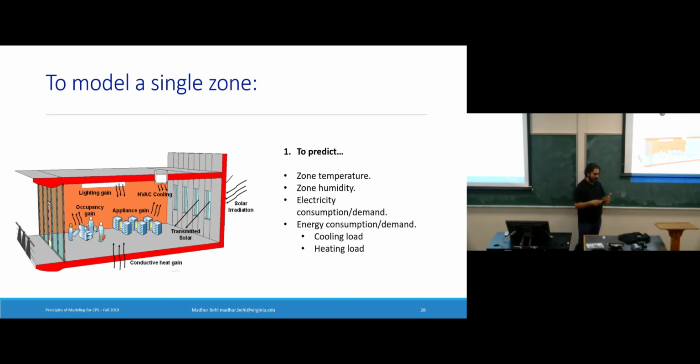And this is the part which is the art of designing a model, right? It's not the science yet. Once you know what kind of model you want, you can make very sound decisions about model structure, and so forth. But there is no oracle which will tell you which model you need. That is defined by the problem in that domain. So for the purposes of this module, we will pick the very first one. It's the most straightforward one. And actually, we have already seen that if you can predict the zone temperature, you can indirectly also infer the loads, the heating and cooling load of the space itself.